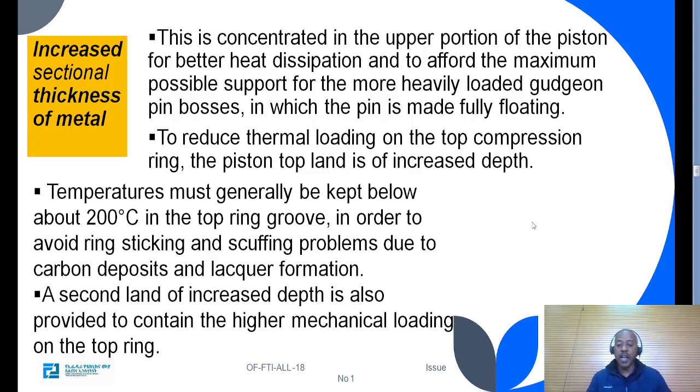Temperature must generally be kept below about 200 degrees centigrade in the top ring groove in order to avoid ring sticking and scuffing problems due to carbon deposit and lacquer formation. A second land of increased depth is also provided to contain the higher mechanical loading on the top ring.